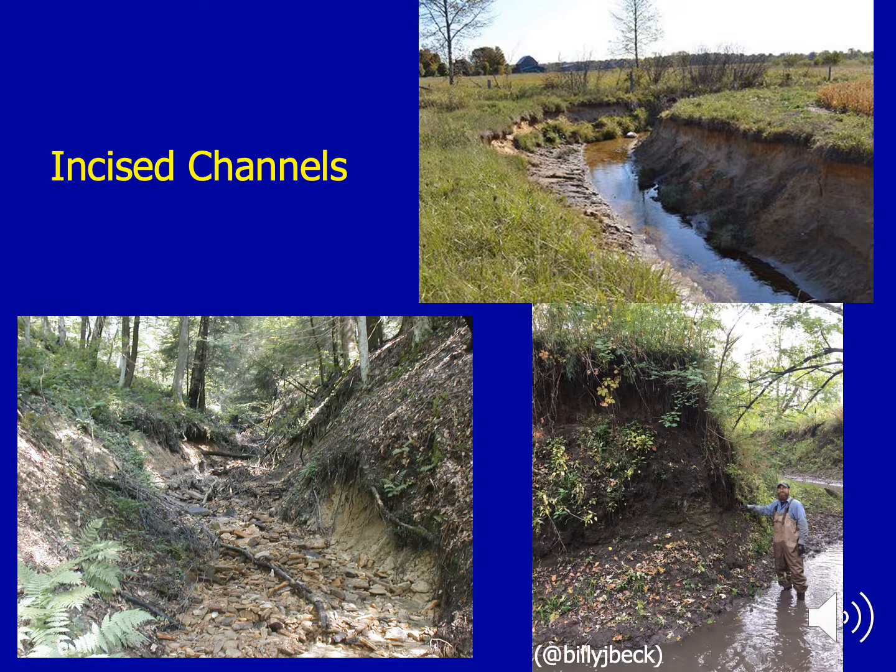When I'm heading out to the field, yes, I'm looking to identify is there an incision or not, but ultimately I'm trying to address what's the magnitude. Can I treat this? Can I work with a solution that can actually reconnect my channel restoration with the floodplain, or, if the incision is so deep, such as here with Billy, it's twice over his head, to reconnect the floodplain. In this kind of situation, you're working within, you're not trying to reconnect.